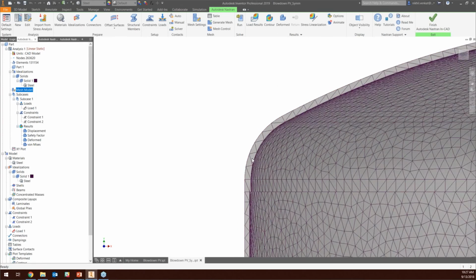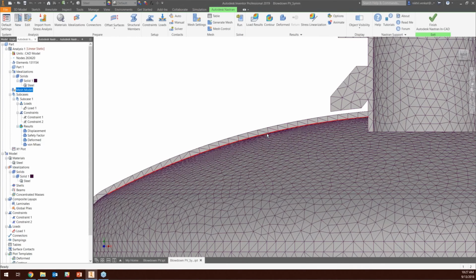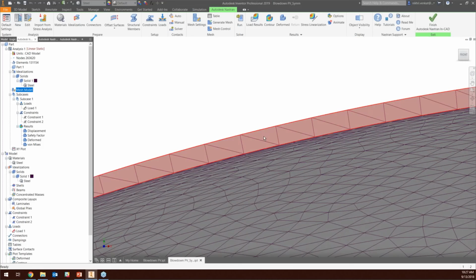I think most of the time the meshing engine forces you to have at least one element in there. It fails otherwise. So you would want at least one element, but again, it depends on what you're expecting to happen through this thickness, right? If you have some very different behavior from one end to the other, then yes, you do want a large number of elements to capture that. If not, and you're just expecting the behavior to be more uniform, then yes, one or two elements is going to be fine. Yeah, it really depends, right?